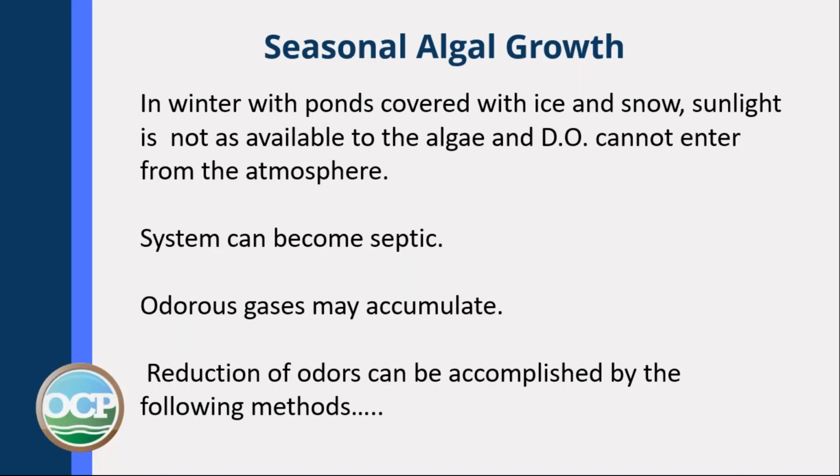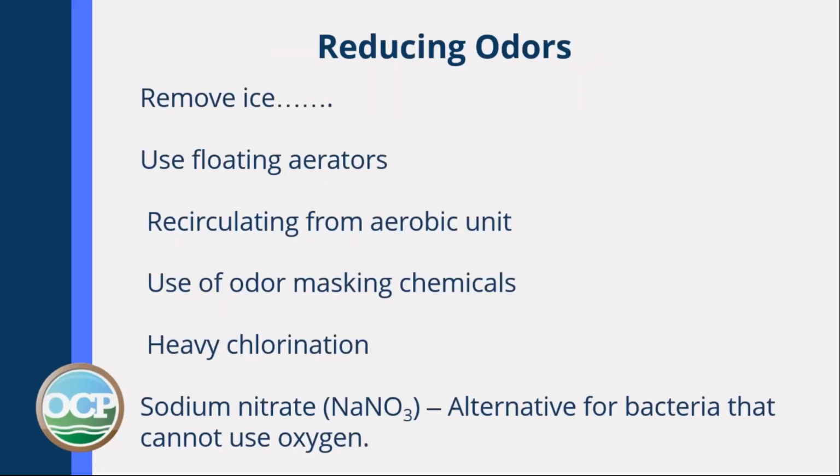You can reduce odors by using one of the following methods. You can remove the ice to allow the oxygen transfer. You can use floating aerators. You can recirculate from an aerobic unit, say an aerated basin. You can use odor masking chemicals, but that just masks the smell.